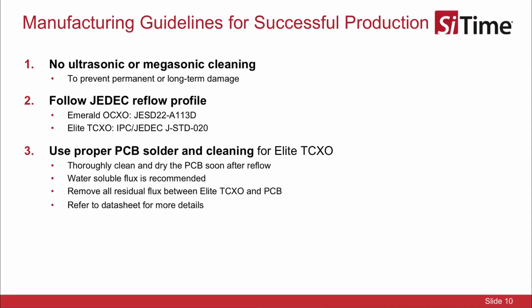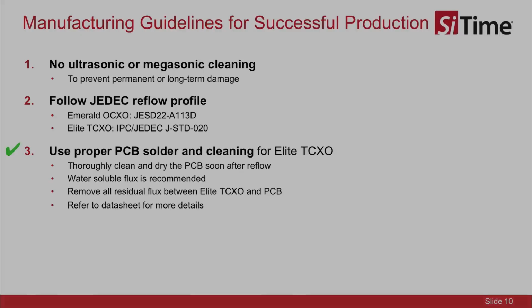We recommend the following key manufacturing guidelines for successful production. To prevent permanent or long-term damage, do not subject SiTime precision oscillators to ultrasonic or megasonic cleaning. Follow the recommended JEDEC reflow profile provided in the datasheet. And for Elite TCXOs, it is important to use proper PCB solder and cleaning practices, which include thoroughly cleaning and drying the PCB soon after reflow, using water-soluble flux, and removing residual flux between the Elite TCXO and the PCB interface. Refer to the datasheet for more details.